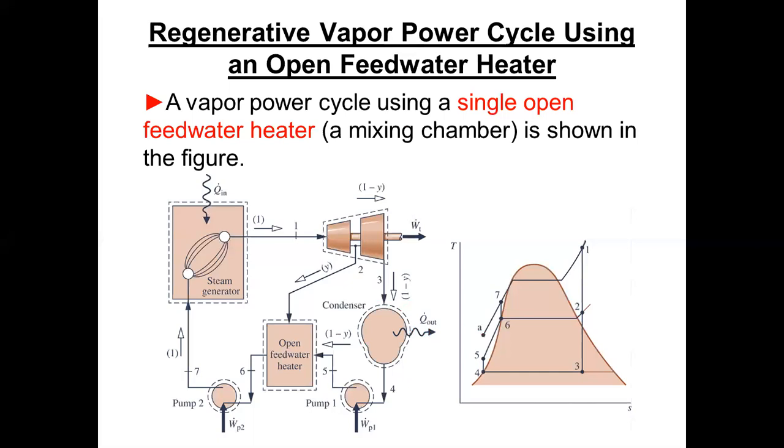So from 2 to 3, again, that's isentropic. And so the power generated in that second section of the turbine is H2 minus H3 times whatever mass flows through there. And so for total turbine work, you would have to add those together.